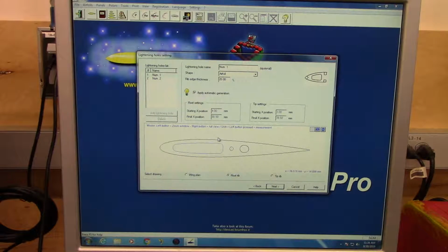However, the wire needs to come in here and cut this top surface and then hollow out the center, meaning that structurally I only have this small member here at the bottom that's holding my wing together. Typically for foam I don't like that. There's ways that you can patch that up, but oftentimes if you apply glue and things in there, you end up making a wing that's heavier than what wing you started out with.